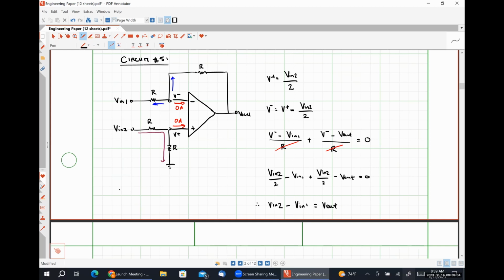So this is what's called a differencing amplifier, because it simply takes the difference of two analog input signals. This is another thing that's commonly seen as an input stage. This doesn't provide any amplification or scaling whatsoever. It simply gives us the difference between two signals, and then we could further scale it by cascading this particular amplifier circuit into a stage with a voltage gain. So put a box around this guy.